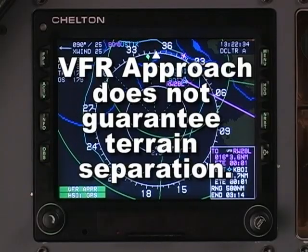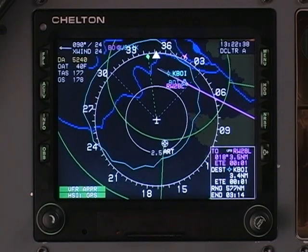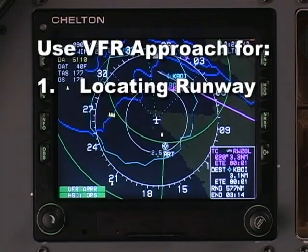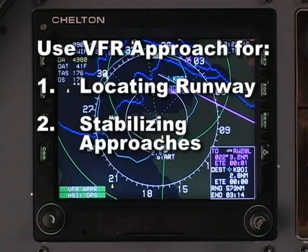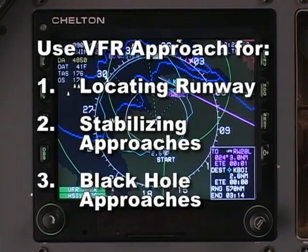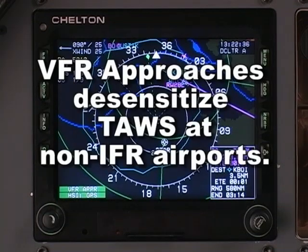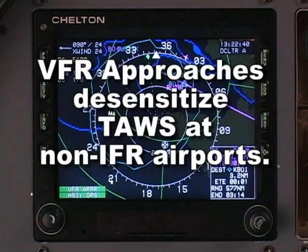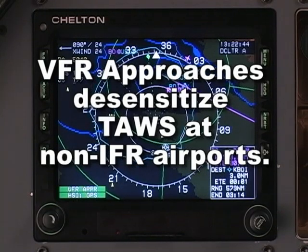The VFR Approach function does not guarantee terrain separation, so it must only be used in VFR conditions. It is very useful, however, for locating the airport and correct runway, stabilizing approaches, and preventing over or undershooting the runway on black hole approaches during VFR at night. Selecting a VFR approach at non-IFR airports will also desensitize the TAWS alerting functions to help minimize false alerts.